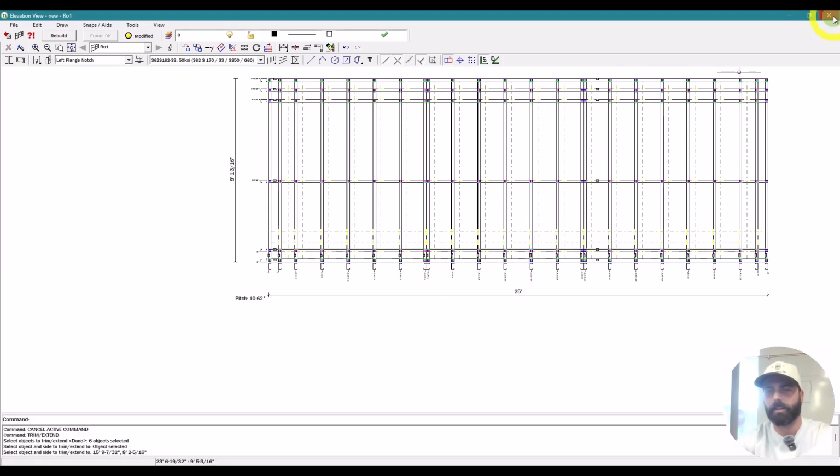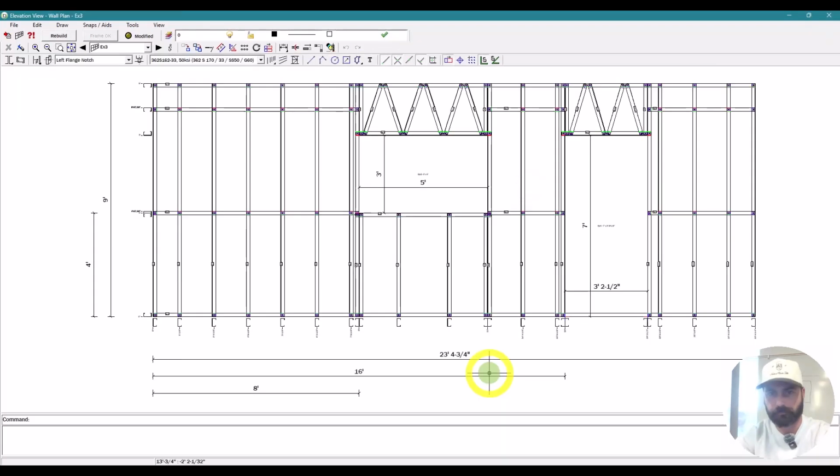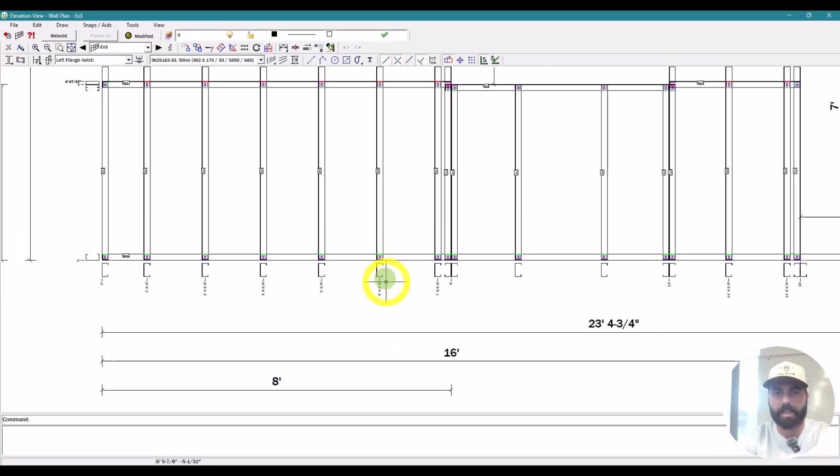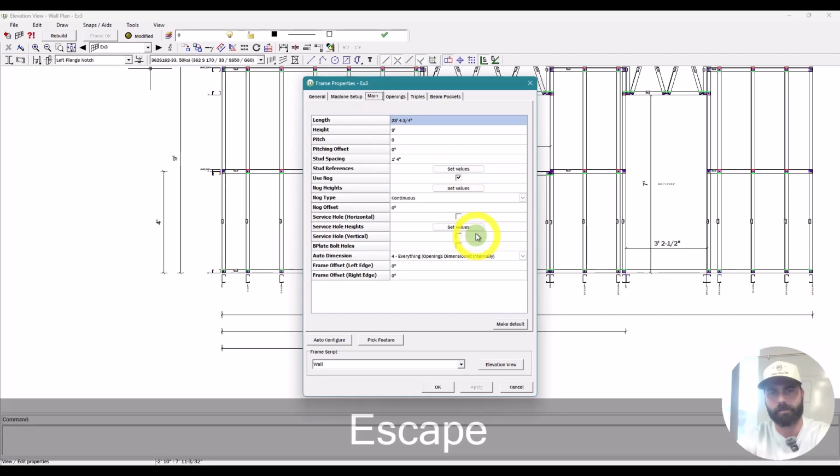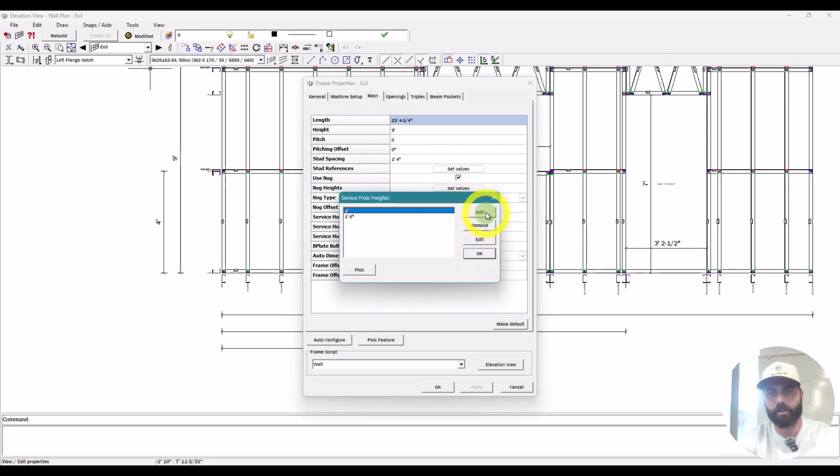We'll go ahead. We're typically doing 18 inches as our first, because hold downs are usually 12 or 18 inches. So if you have a 12-inch hold down, you want to make sure your first run of electrical cables is above that, so that you're not missing an entire run, having to go up, over, and around the hold down. So we'll typically do 18. I'm going to edit this one, and we could do 32 inches, right? And then we could do 3'6", 1'6", 3'6". I'm going to do 7'6" instead.